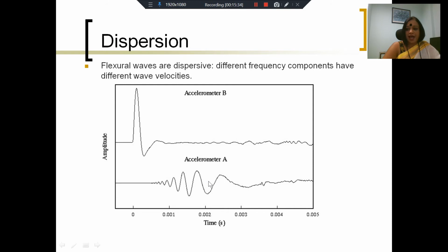However, imagine accelerometer A, which is positioned quite a distance away from the PD position. Now, the various frequencies will travel at various velocities. The result would be that a wave that looks like this, and that is what you're expecting at your sensor location, so that you can figure out what is the time taken to travel, therefore what is the location, etc., arrives like this.